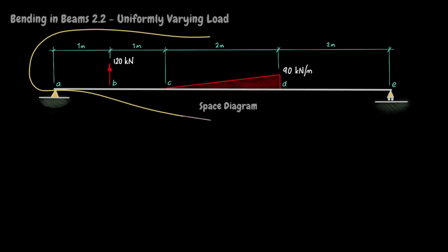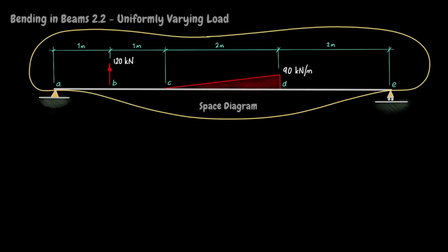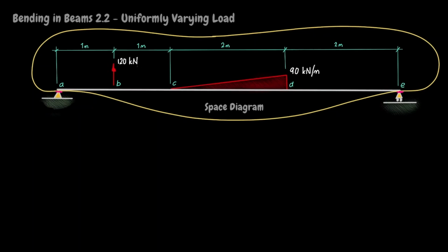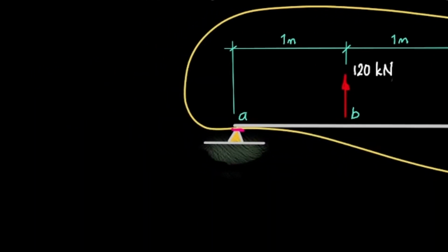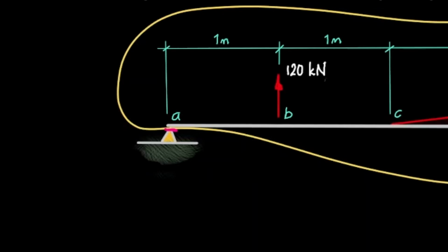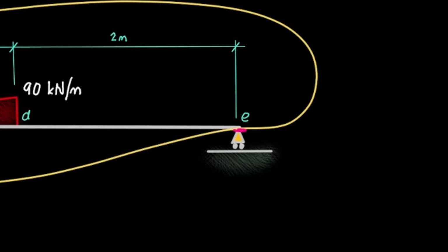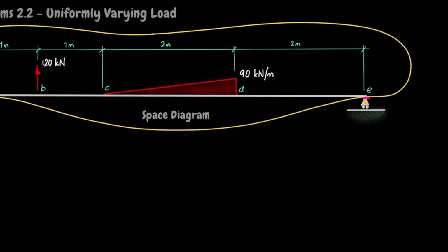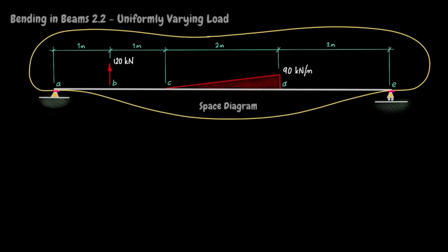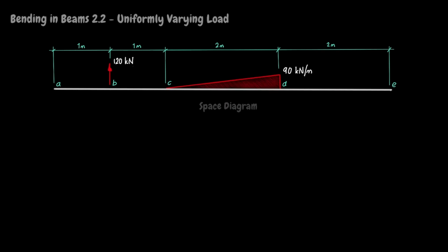Draw a free body diagram bubble that cuts the beam away from its supports. The purple lines represent the cuts, and these cuts expose the unknown reactive forces. If this makes little sense to you, then click the link on the screen to find out more about cuts, free body diagram bubbles, and all sorts of cool stuff. Next, remove the supports and replace them with the forces that have been exposed by the cuts.